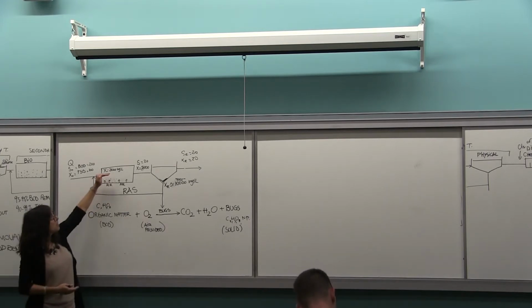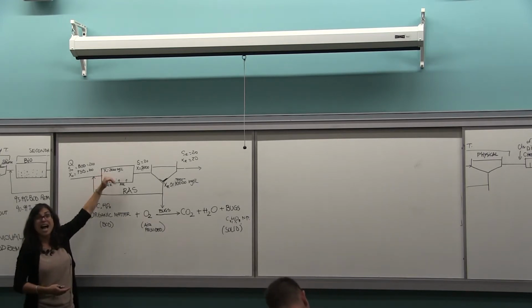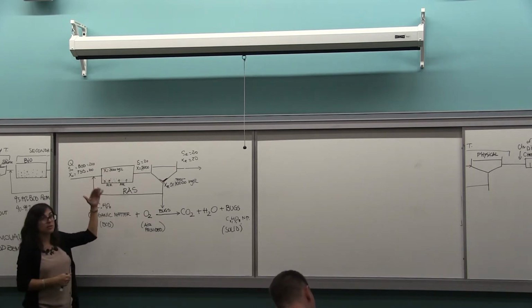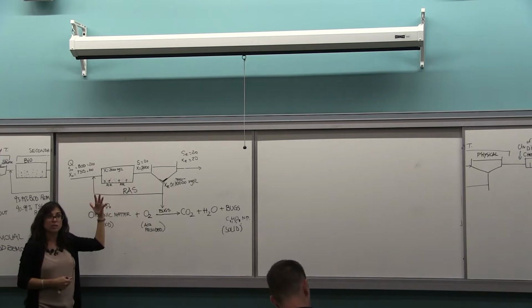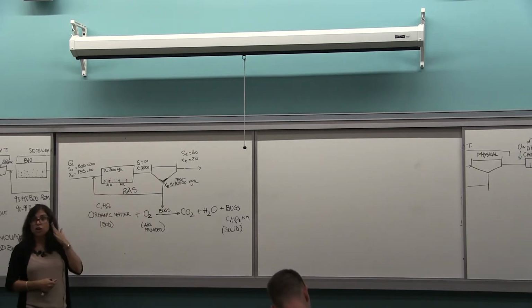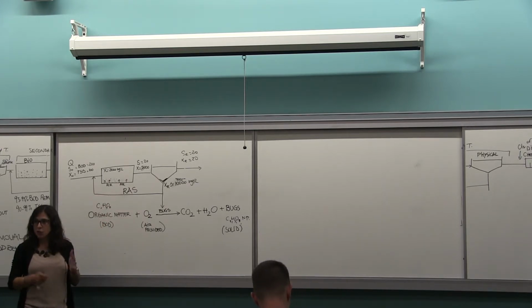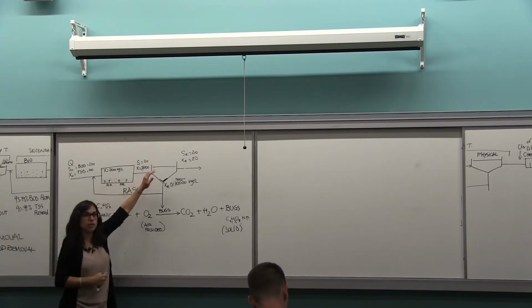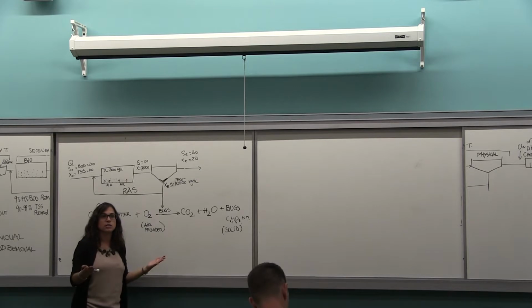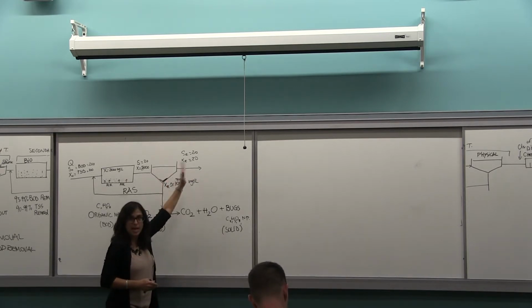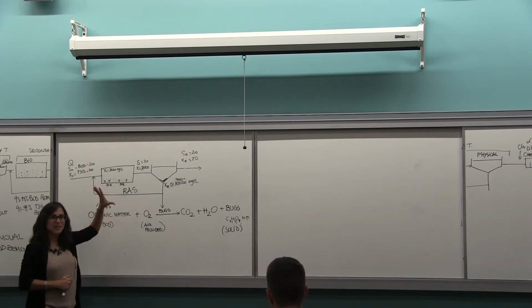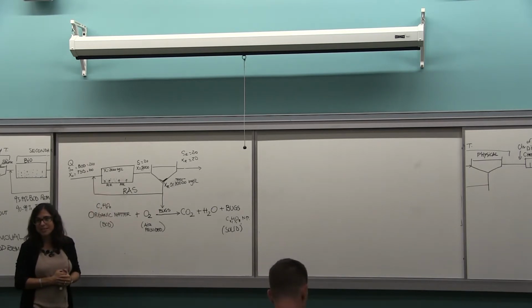So there is a physical limitation to how many bugs we can incorporate in there. 2,000 to 3,000 is typical, the concentration of volatile suspended solids of bugs that I can keep in there before your clarifier crashes, essentially. And then you will have solids out. All right? So this is what an activated sludge system looks like.